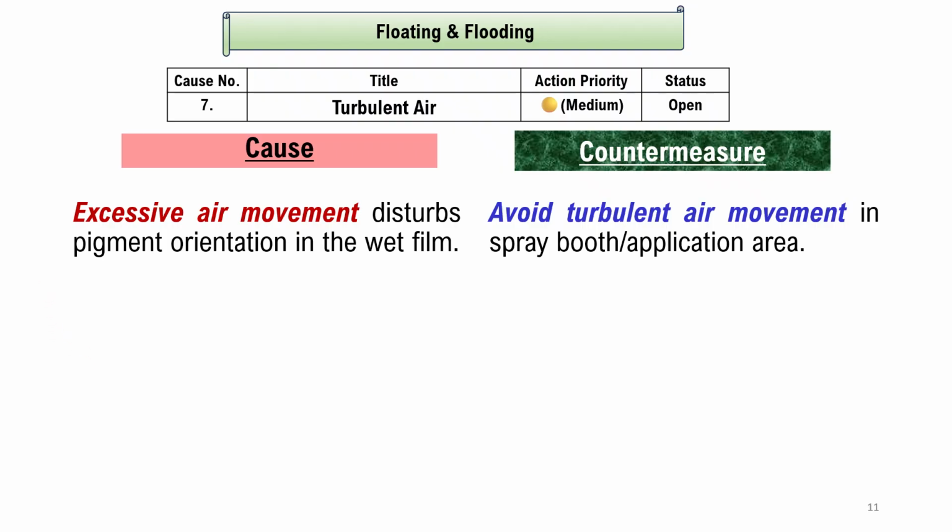Number 7. Probable cause could be turbulent air. Excessive air movement disturbs pigment orientation in the wet film. Therefore, avoid turbulent air movement in spray booth, or otherwise called application area.